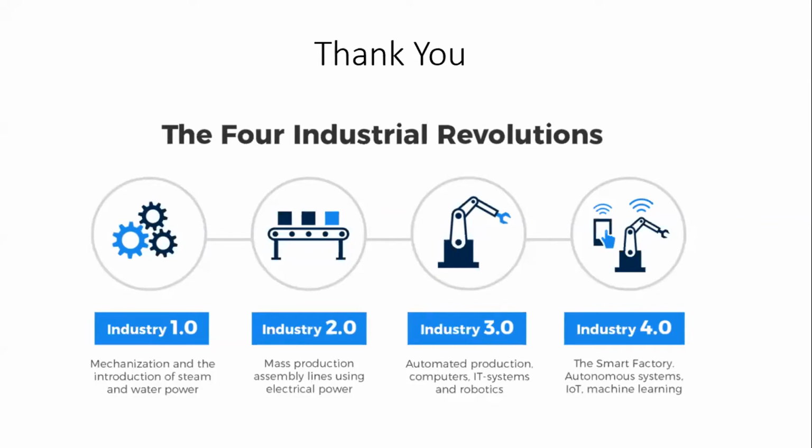So what he has asked is, does agglomeration of the particles occur when mixing materials like, say, hybrid material like niobium and the zirconium 50 you talked about, or when passing through a nozzle onto the bed? If it is happening, how is it managed? So fortunately for LDED, agglomeration does not occur. It can happen in laser powder bed, possible, because when you're doing the spreading, unless you have control over the dynamics of fluid, this is where chemical engineers also come in. You need to understand the dynamics of particles in the powder bed.